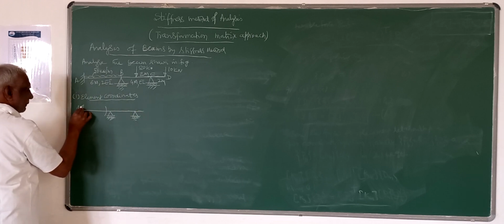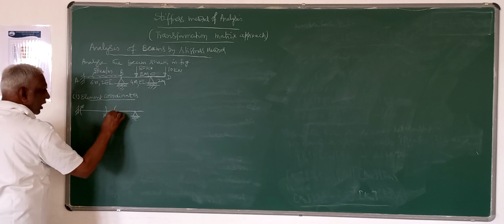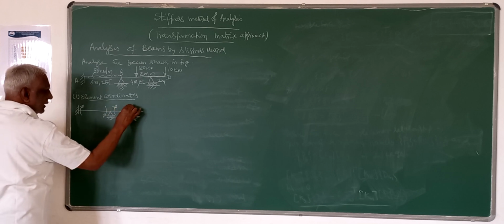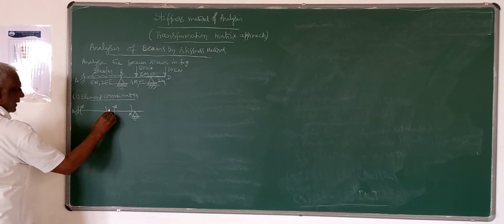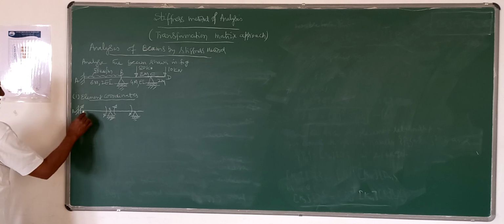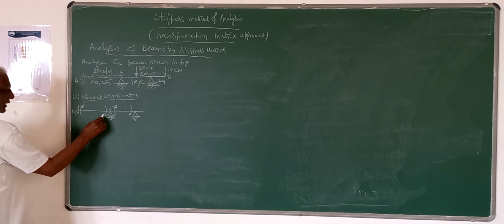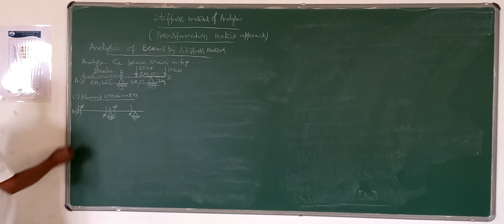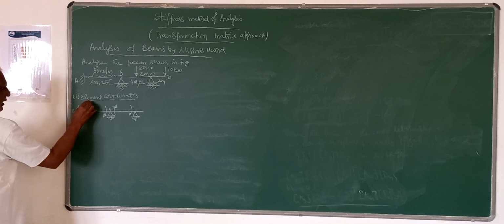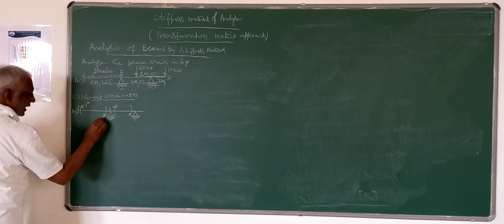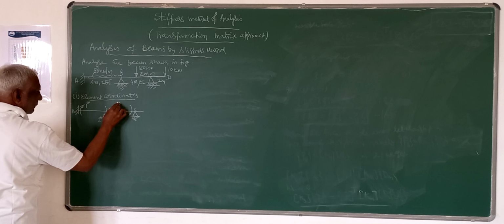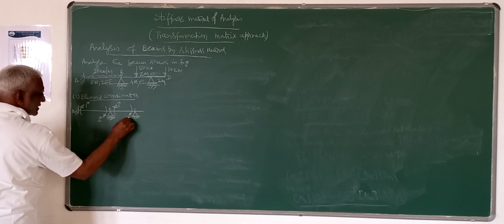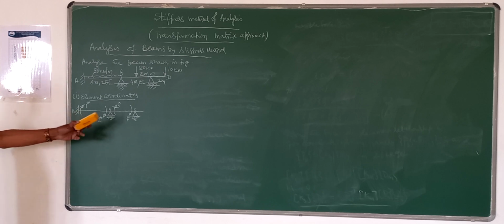So for these internal member forces, we always select the moments at the ends. So in this member AB, the moments at the two ends whose direction in clockwise is taken as positive. So this is called coordinate 1, this is element coordinate 2, and for the BC member, similar to AB, there are two coordinates, that is the moments at the ends in the clockwise direction as positive.